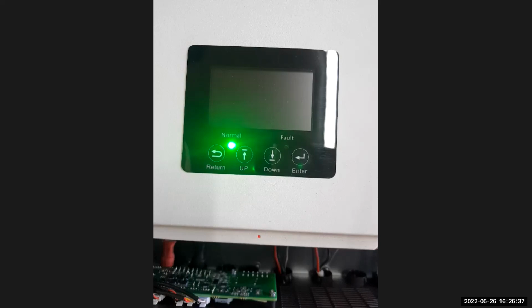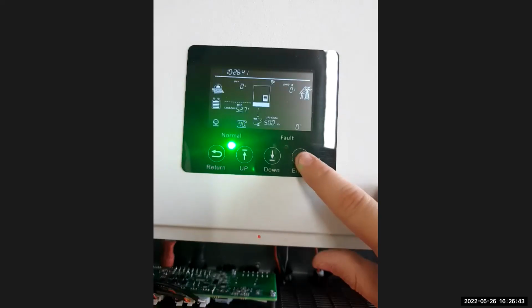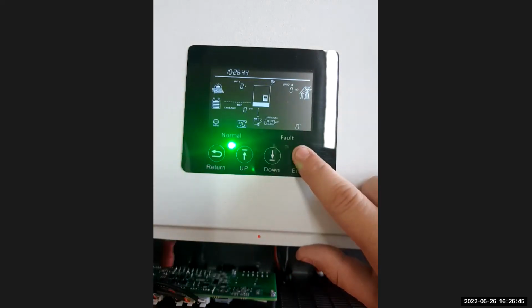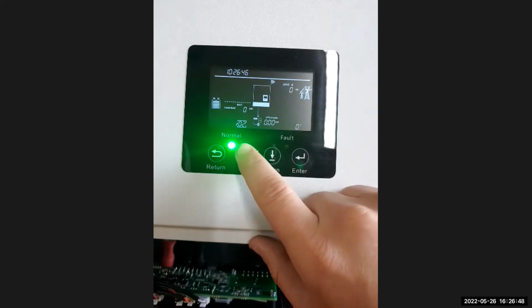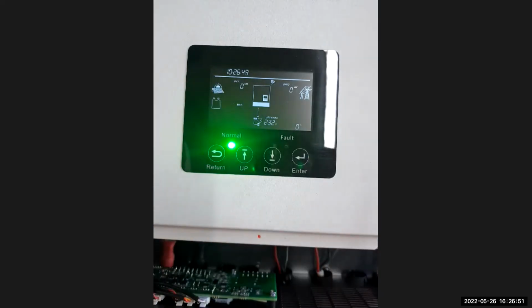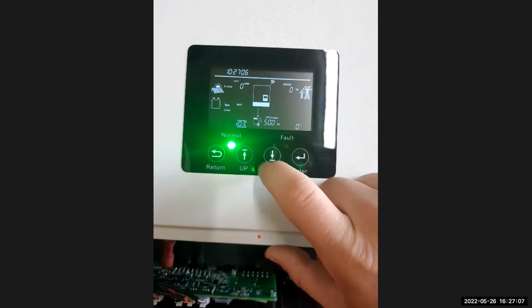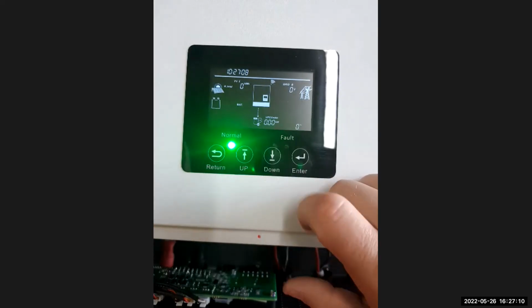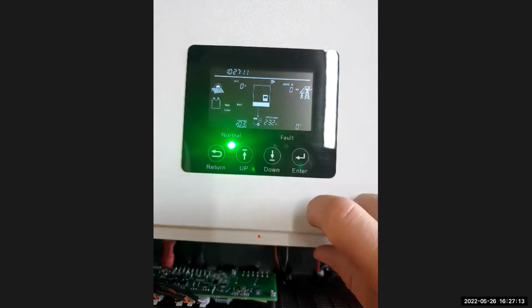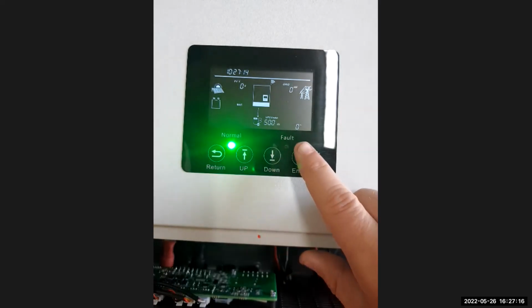if you start up your inverter, the first settings that you'll have to do are your battery settings. That's setting number 3. Keep your enter button pressed until you hear the beep change. Then you go to setting 3, and that's where you select the type of battery that you'll be using on this inverter. For instance, I have a lithium battery here that I just didn't communicate at this moment. So I put it on lead acid settings so that I can run it on user-defined voltage settings. But you can decide if you want to use lithium or lead acid or no battery at all. So we leave it on lead acid battery.